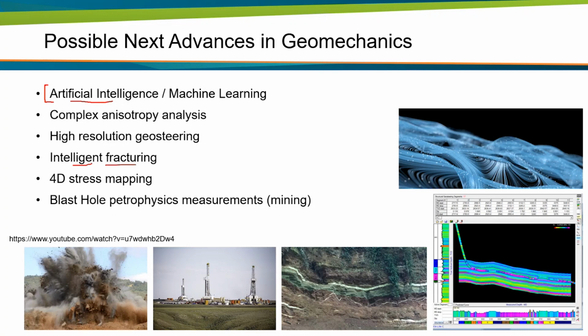So you monitor your data and where microseismic events happen, and you adjust your fracture pressures and your injection locations according to the data you get to maximize or to make the best out of the fracturing job you are doing.